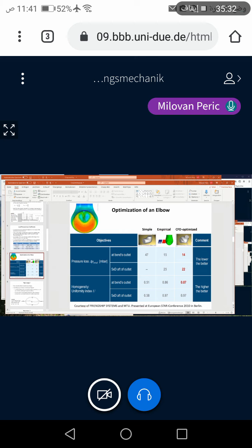In the middle part, you would have half flow going backwards, because the flow would tend to go to the outer end straight, and then will be by pressure forced to go along the other direction. You have strong recirculation. So this squeezing makes it that you avoid this recirculation. And actually, many of these 90-degree bends that you have in piping, they are produced by casting. And to cast this optimal shape is no more complicated than to cast the simplest 90-degree bend.